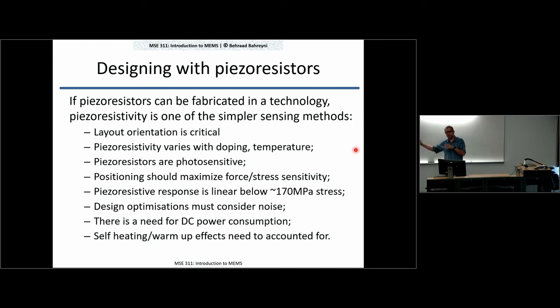But here come new challenges. If you use a small current, well, a small current times the resistance means a small voltage. Your signals will be weaker. And there has to be a balance somewhere, right? So you look at your device and maybe ensure that the heat is dissipated very well from your device so that it doesn't heat up with a slightly larger current, or come up with techniques that basically take the self-heating into account.